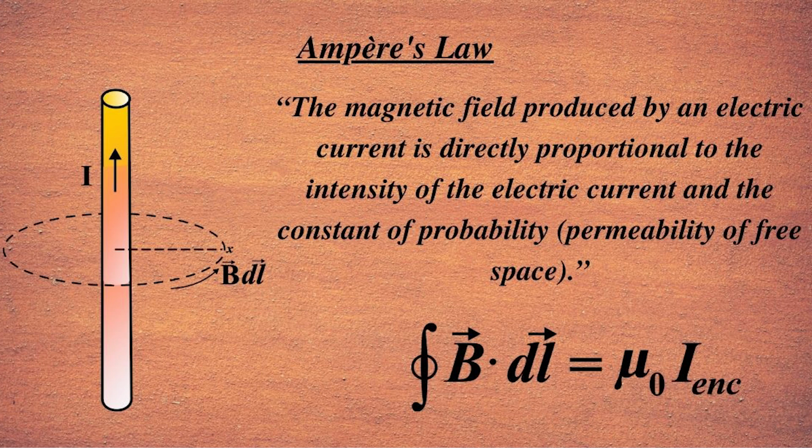The relationship between this magnetic field intensity H and the resulting magnetic flux density B, which measures the strength of the magnetic field within the material, is given by B equals mu H, where H is the magnetic field intensity we have already seen, mu is the magnetic permeability of the material, and B is the resulting magnetic flux density produced. This expression is used throughout in magnetic circuits.